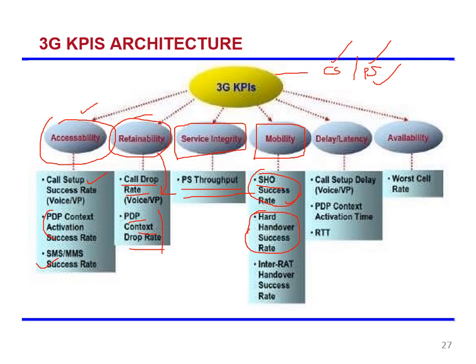When the frequency is changed during the handover, it's called hard handover. When the frequency is not changed during handover, it's called soft handover. Usually soft handover will be there in 3G mostly. Hard handover will be there if you are having more than two 3G frequency slots. Of course, in BSNL's case, we are having only one frequency slot, so it's not an issue.